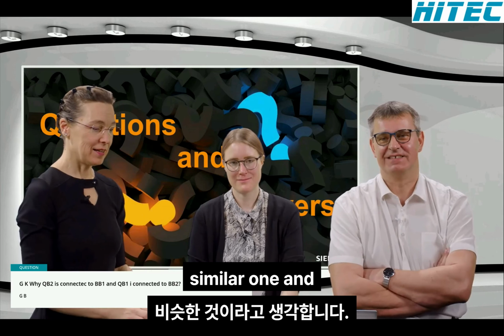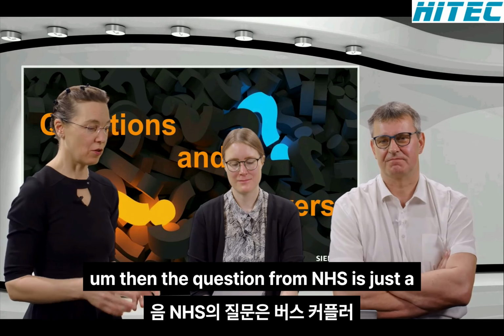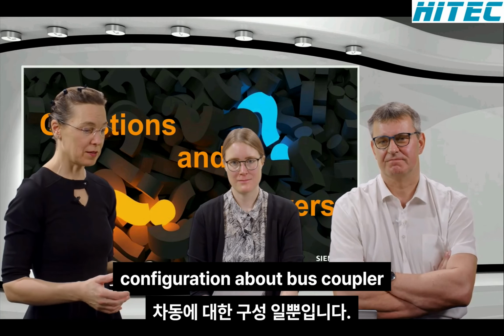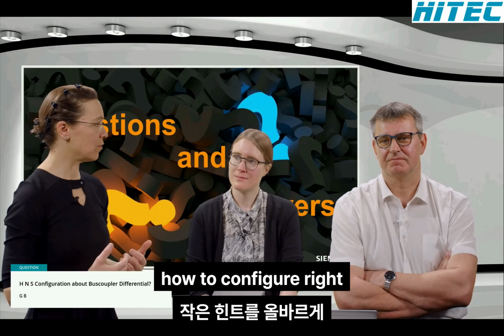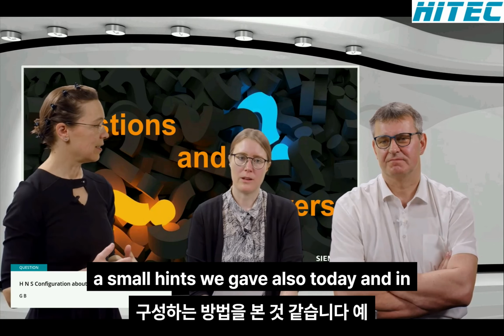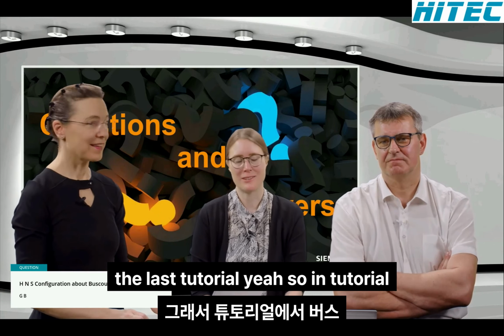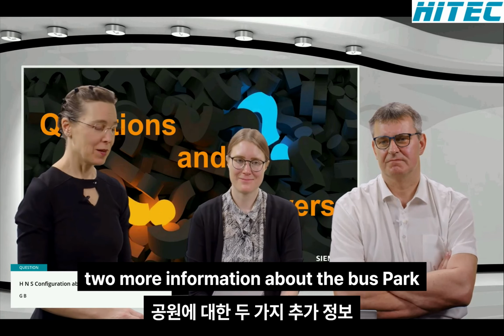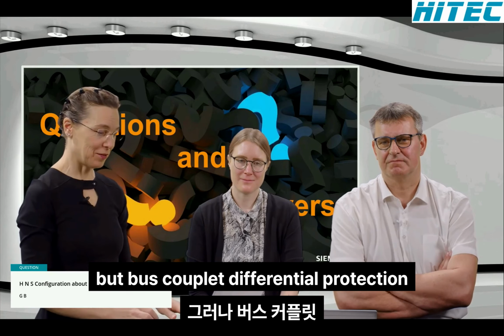Yeah. And then the question from NHS is just a configuration about bus coupler differential, and I think we've seen how to configure that, right? Small hints we gave also today and in the last tutorial. Yeah, so in tutorial 2, more information about the bus coupler differential protection.